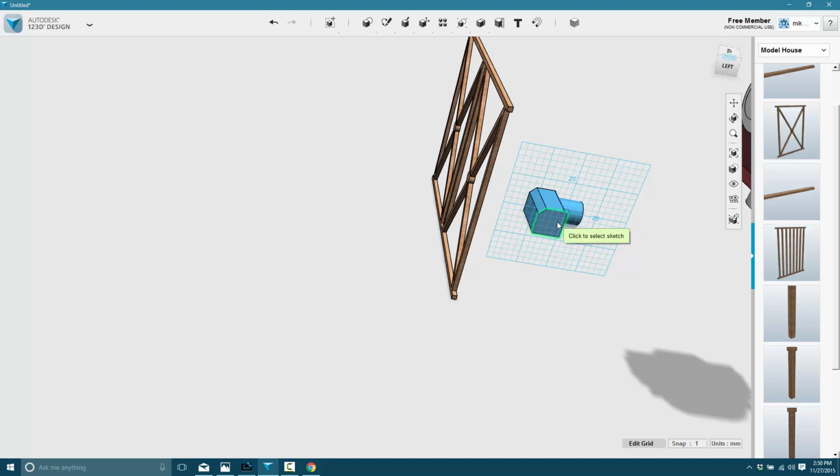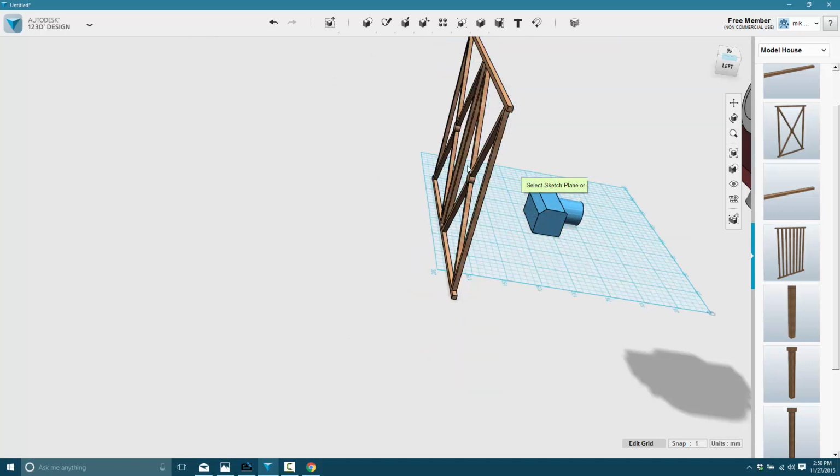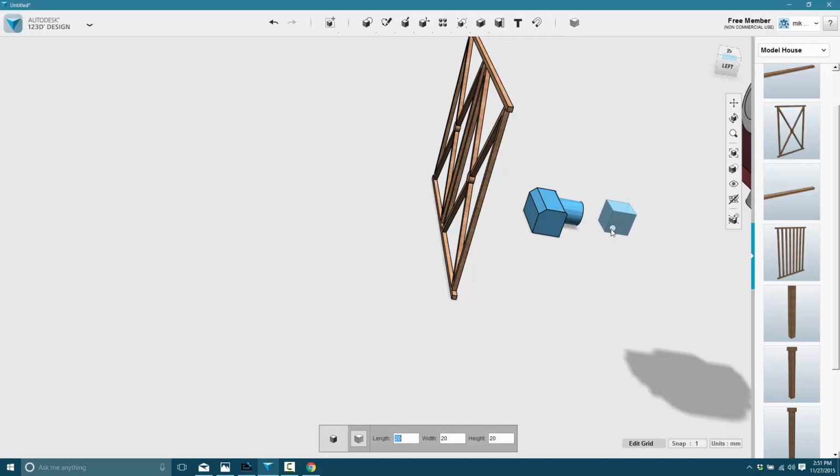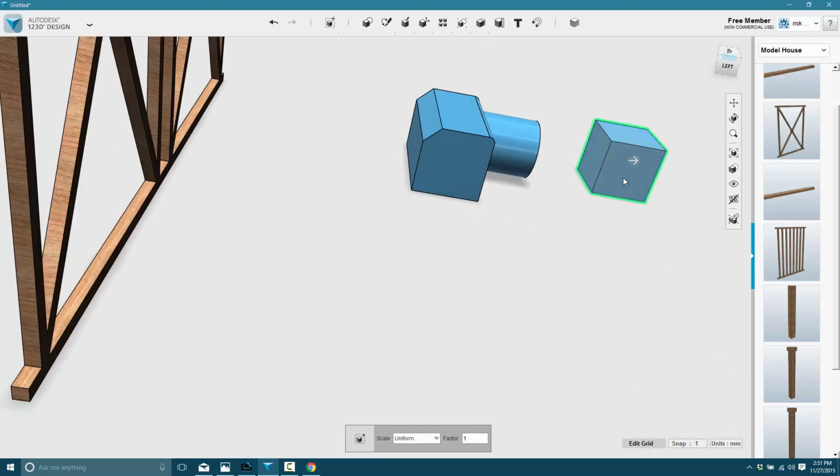You could actually do things like, I could build the autocannon for a mech in seconds. Make a single rectangle, put two cylinders through it, chamfer the rectangle down, do an intersection, bring it in, start beveling holes. You can do things like, when you're filleting or adding detail, we could, all right, scale.